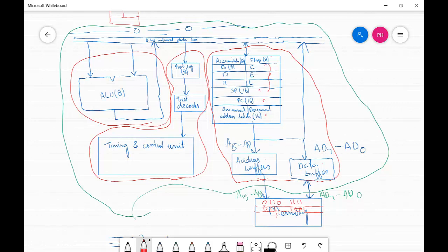So when we power on our microprocessor, in most microprocessors, this program counter, which is 16-bit wide, will have 0000, all zeros, 16 zeros. I am writing in hexadecimal, so I will put an H here, to make these things short. 0000 means all zeros. Program counter will have 0000.